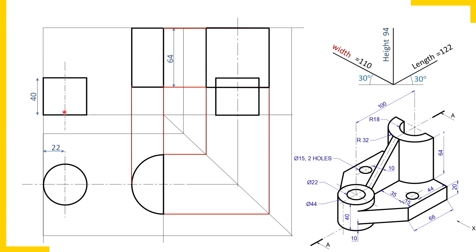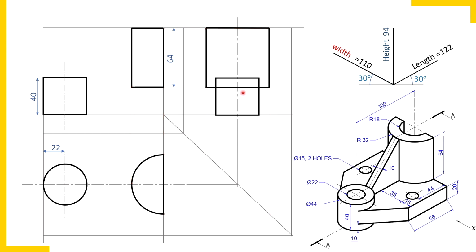So the cylinder is nearer to the observer. So the semi-cylinder's overlap portion, which is exactly behind the cylinder, is hidden, and that is why the overlapped portion of the semi-cylinder, this portion, you should draw hidden. Have you understood that? No intelligence is required to understand.